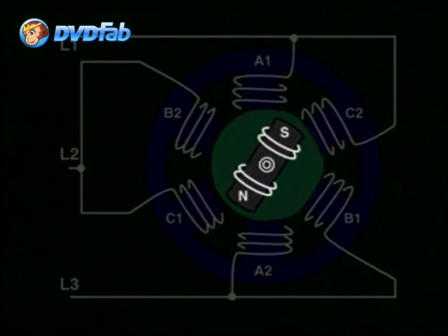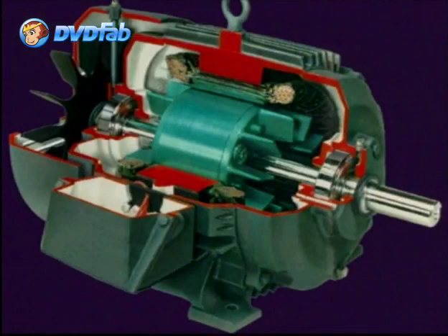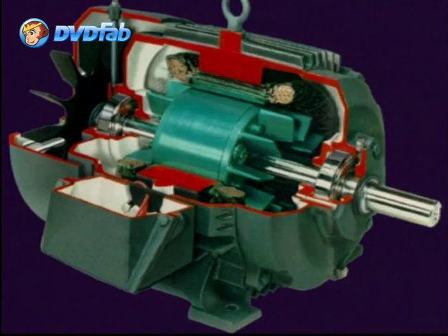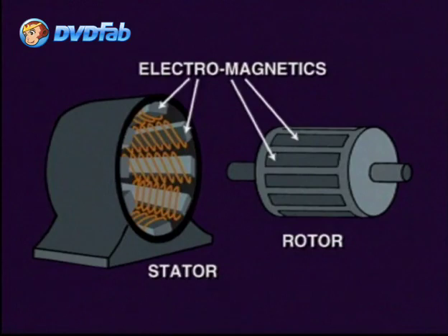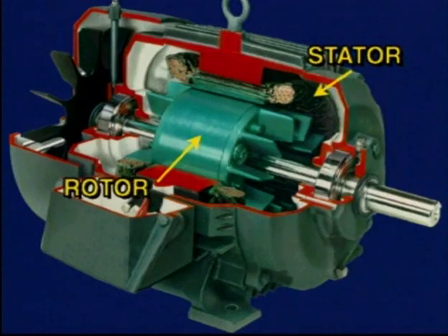The rotor, as its name implies, is the rotating part of the motor and is constructed from either coils of wire wound on laminated steel, or it can be made from all laminated steel without any wire coils. If a motor's rotor has wire coils, it is called a wound rotor motor. A laminated motor rotor, which is most popular nowadays, is called a squirrel cage motor because the design resembles the cage used for pet hamsters and the like, and therefore its name. As you can see, there are no brushes to pass current to the rotating parts, as was the case in a DC motor. The current is induced from the stator field to the rotor.